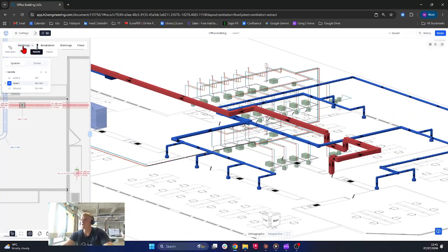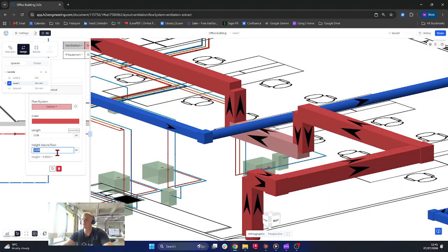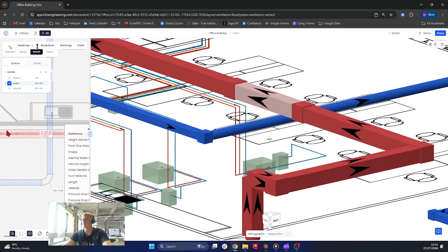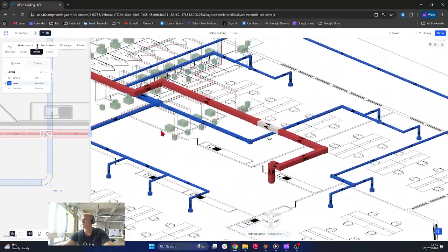If you want to make any alterations, we know that we can bring that up to a larger height. We just need to click onto it in the 2D mode, back in design mode, bring it up to a height of 3.4. Rerun our results. H2X will get rid of the 4 additional elbows dropping down and coming back up, and that will recalculate the index node path resistance for us.